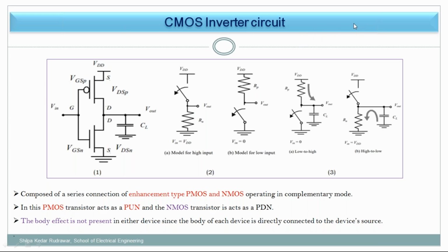And the last and very important thing: to avoid the body effect, suppose this is the PMOSFET and this is the NMOSFET. Suppose VT of this MOSFET is minus 0.7 because it turns on at a negative voltage, and VT of this one is plus 0.7. These should be matched, meaning it should be 0.7 and 0.7, not 0.7 and 0.6 or 0.5 and 0.6.